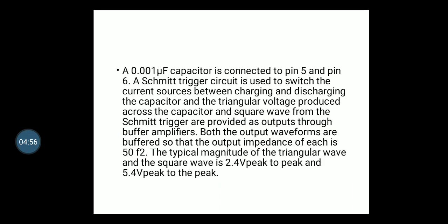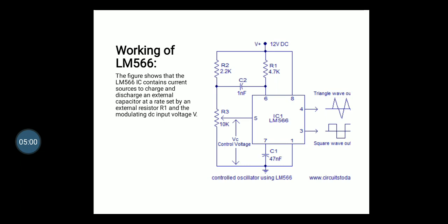The output voltage of the Schmitt trigger is set to a level of VCC and 0.5 VCC. If RA is equal to RB, then through the positive feedback path, the voltage at the non-inverting input terminal swings between 0.5 VCC and 0.25 VCC.